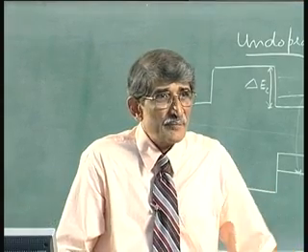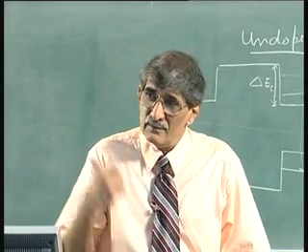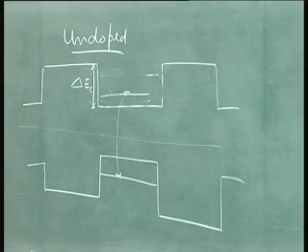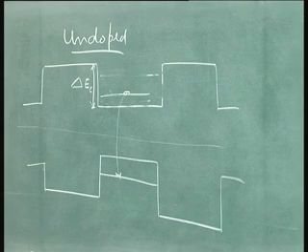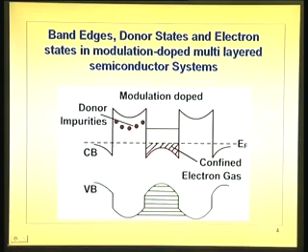But here what we are talking of is the transistor, you do not need multiple layers. But I just show one more diagram. So, this is N-N uniformly doped, doping here is the same as here. Okay. Still there will be transfer of electrons from here to here. Now, you have another situation that is called modulation doped. Okay. The transistor that is made out of this is called MODFET, modulation doped field effect transistor. That is also called, it will come later, that is also called high electron mobility transistor.